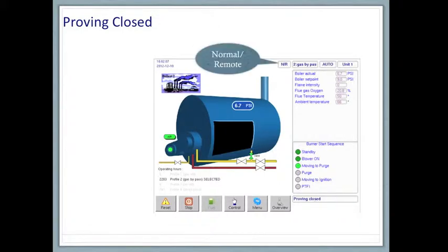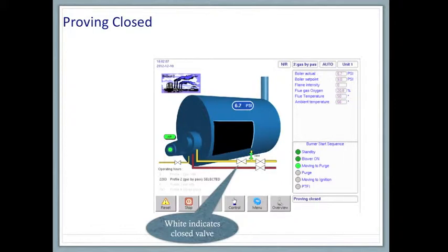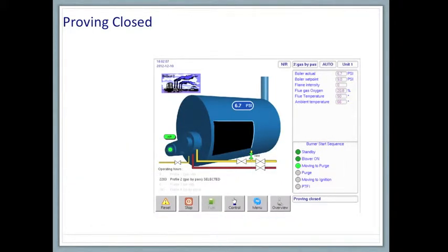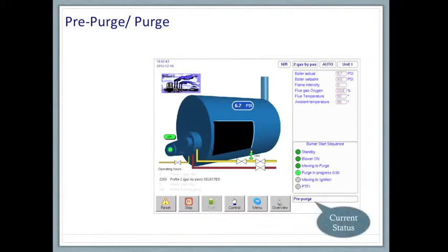If a fuel profile is selected and the controller recognizes a call for heat, the boiler moves all drives into their purge position. Then, the controller purges any remnants of combustible fuels left inside the chamber before attempting to start. Using the blower fan, air is forced through the boiler for a predefined period, usually 30 seconds.